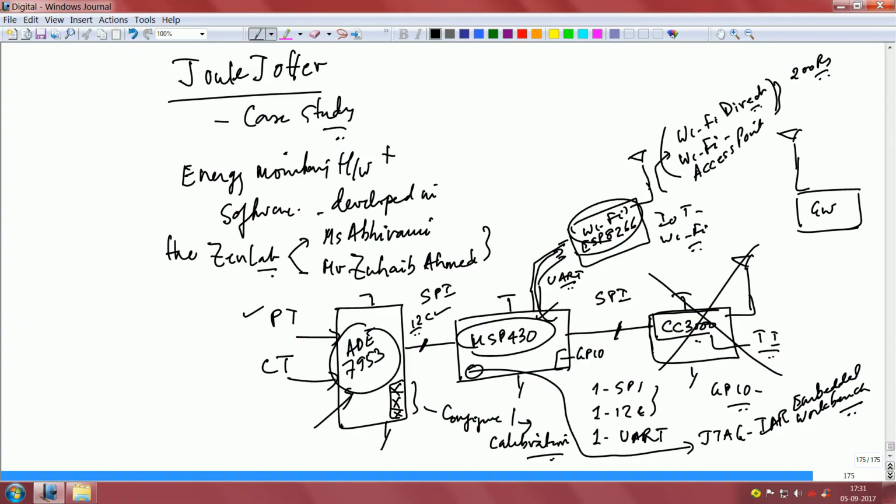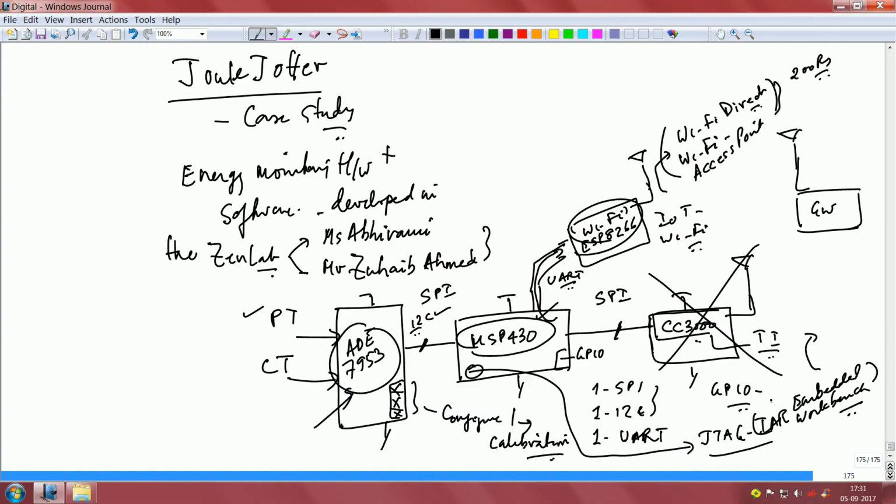So you can see that you have to program this MSP430. You need a JTAG port for that, and on JTAG we use this tool called IAR Workbench. It is a very powerful environment under which one can develop code for the MSP430. Different targets are available, and we have chosen the MSP430 as the target processor. So we have used IAR Workbench for all the code development.